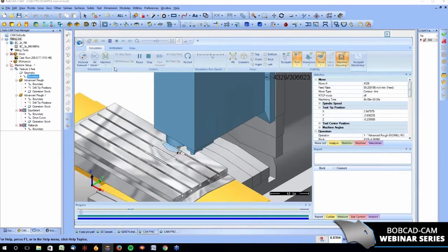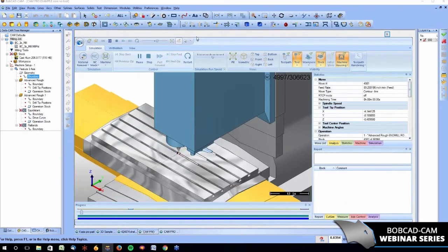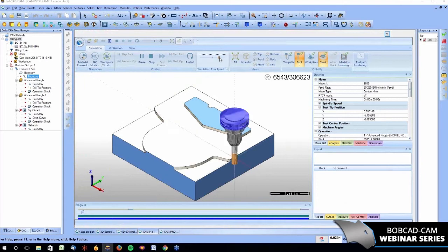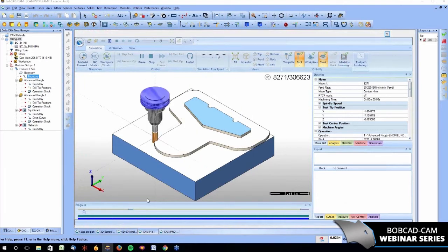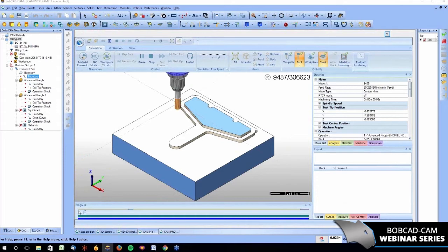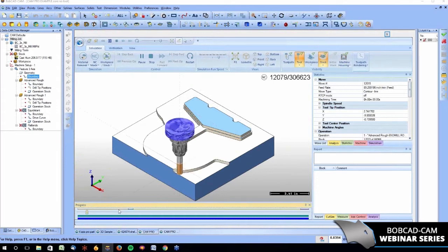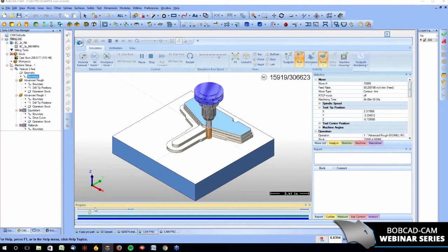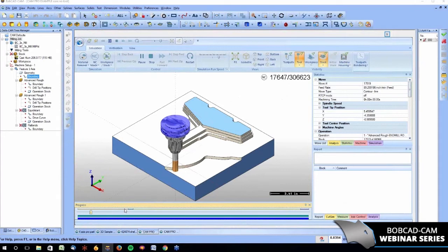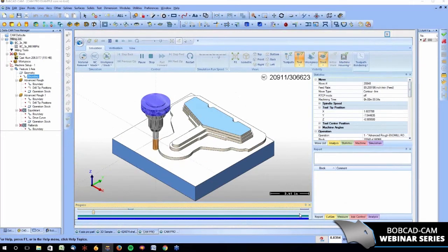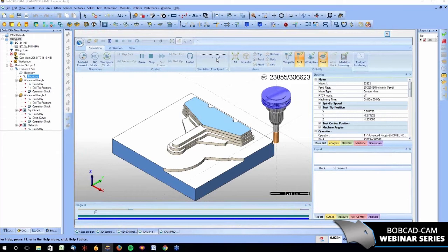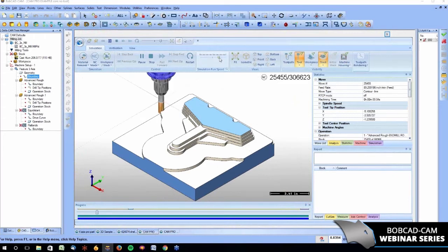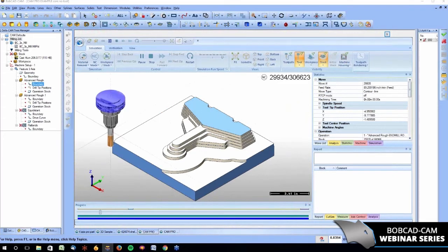So what's nice is I'm going to go ahead and shut this back off, okay? Let it continue through the simulation so you guys can see. The nice part too, if you guys look down here, I don't know if you guys have ever noticed in your simulators that we actually have the little line targets. These are where it changes toolpaths. So we know that we have the rest rough, or the advanced rough, then the rest, then the equidistant, and then the flatlands is a different color. So we can go ahead and speed this process up because we need to go in and make some.